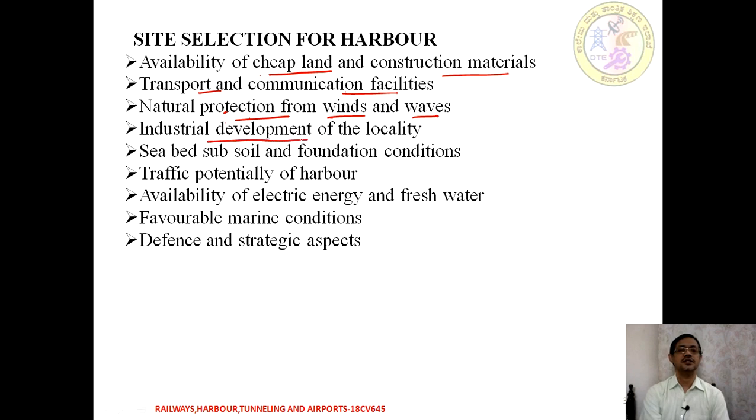Next, the industrial development of the locality, seabed, subsoil and foundation condition, traffic potentiality of the harbour, then availability of electricity or electric energy and fresh water, favorable marine conditions, defense and strategic aspect. So, these are the points to be kept in mind while we select a site for a harbour.